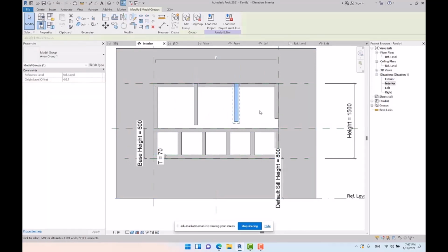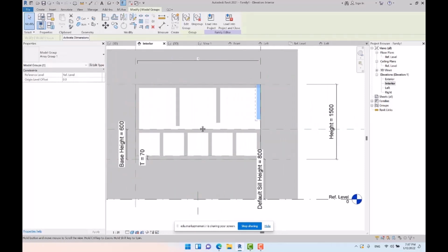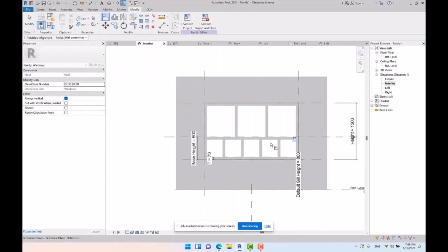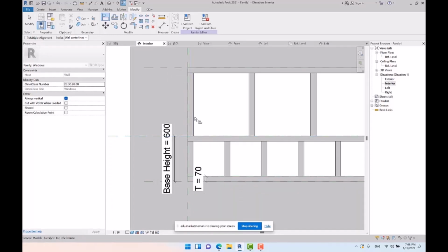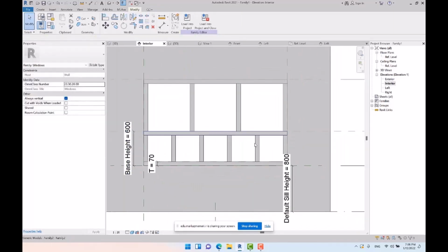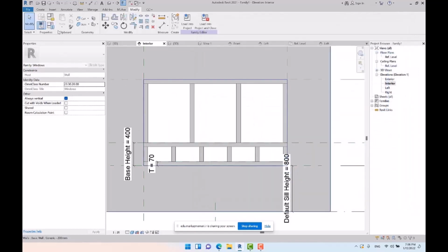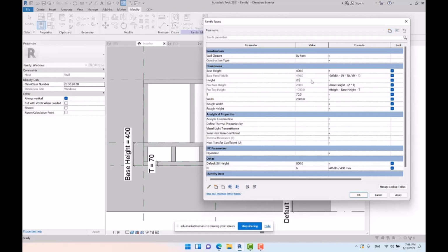Watch this part please. You may have such a problem. The height of the profiles in the top part are not similar to each other. This happens when we align to a specific object and then use the array tool for duplication. You should align them with the reference plane and lock again. Let's check it out. Otherwise, the previous problem would occur, but right now it is fixed by just the alignment and also locking it to the reference plane. So again, if I modify the value of width, we will see whether they are working correctly or not. 400 for example. Okay, as you can see, they are aligned with the reference plane.